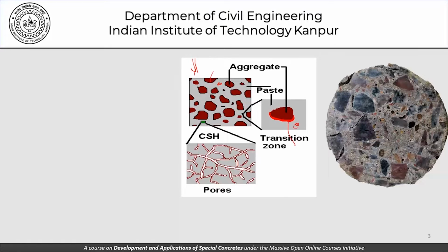Now around this coarse aggregate and mortar, we've talked about this transition zone, and this is what we have called the main body mortar. If we look at a small part of this main body mortar, the way it is expanded into this small inset, we have these as the solid hydration products, which we can call hydrated cement paste, and we have these as pore spaces.